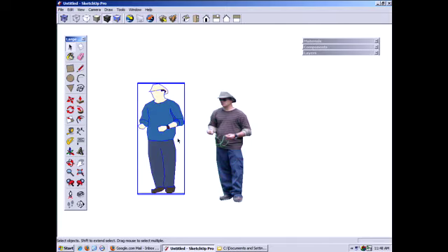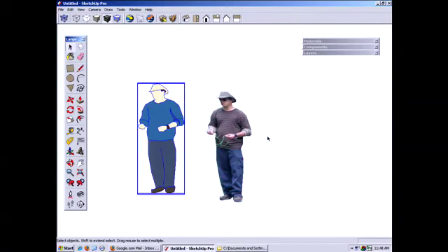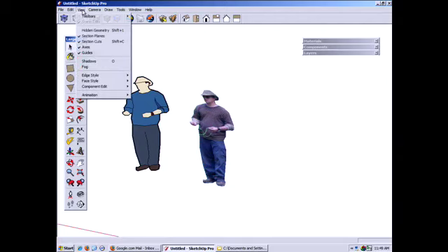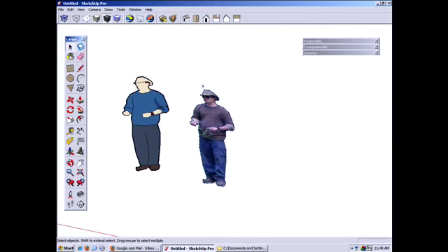Yes? Could you guys do that again with setting the axis a little higher on the screen? Was it not shown? Yes, let's do it again. Let's do it on this component. I'm going to select this component. Just to be sure, I'm going to go into View, Hidden Geometry, just to make sure I select all of its edges as well, all those edges that we hid, and make that a component.